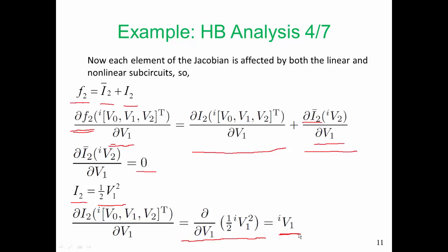These derivatives in all commercial code are developed manually and they're incorporated in the transistor model or the diode model. So writing these models is a very laborious exercise, with the result that there are not a lot of different types of models in the simulators. In fact, that's one of our big research problems going forward: how can we come up with models much faster, instead of spending 2 or 3 years developing the model that we can use in a harmonic balance simulator. It's much faster to develop a model that will be used in a SPICE-like simulator.